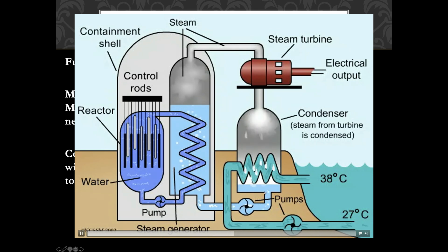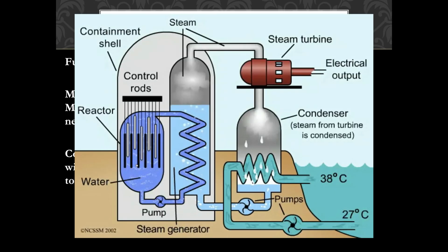The steam condenses back into water and is pumped back in to be turned back into steam again, giving you 3 loops, 2 of them closed, 1 of them open. No radioactivity will actually transfer between this first loop to any of the other loops. Isn't that loopy? In any other power plant, this reactor core would be replaced by a furnace, which would burn coal, oil, or natural gas. But that would also produce air pollution, and nuclear fission reactors do not produce air pollution.